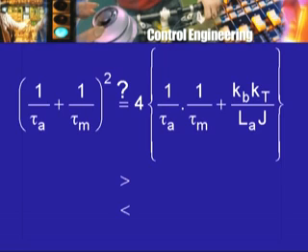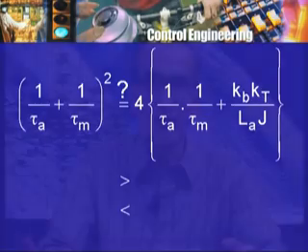But in all cases we are safe because the poles of the transfer function are in the left half plane. They are all good poles. This is something we can conclude because in this case we simply have a quadratic, and so the work was easy. The root locus method enables you to draw some such conclusions when there are not just two poles, but there may be more than two poles, and there may also be zeros, that is, there may be terms in the numerator.